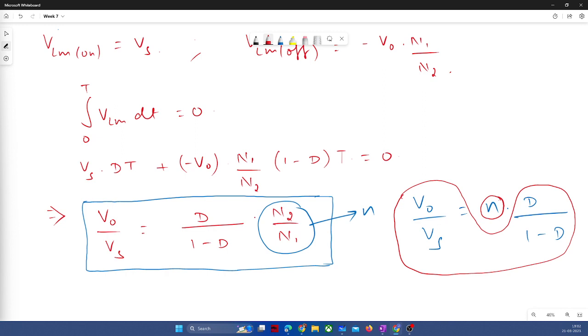So for what value of duty ratio, since you fixed your number of turns, you will have to compute the frequency of that converter. If the controllers with variable frequency as well as variable PWM from the same controller are available, you can certainly vary the frequency with controllers. Variable frequency and variable PWM is available there.